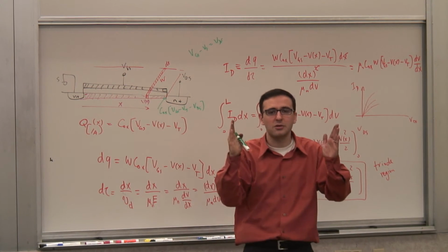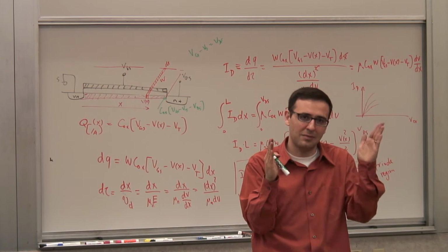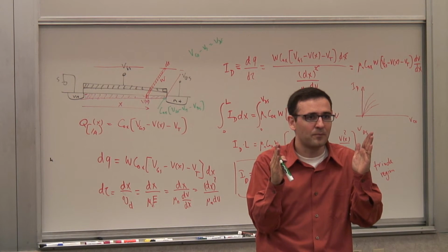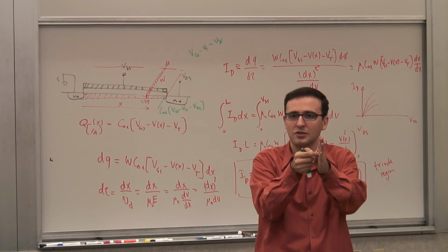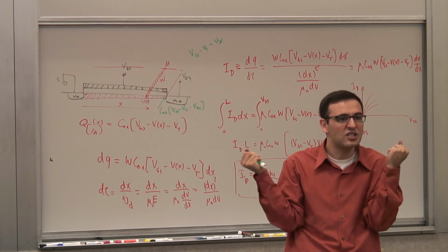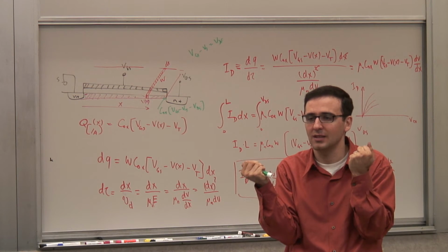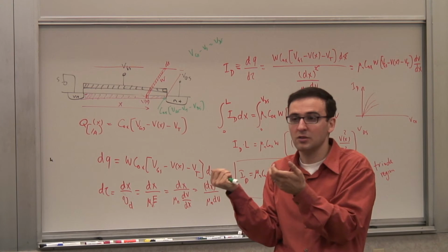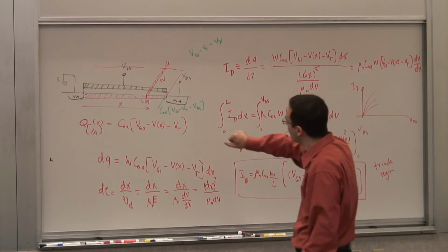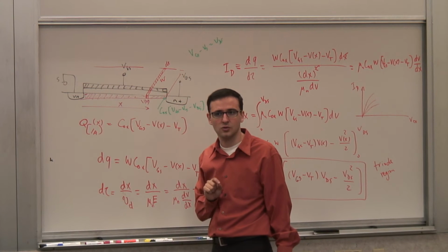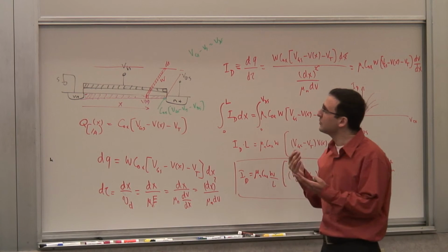The same way in the base of the transistor, you remember when we did this exercise, on the collector side, because everything that gets to the edge of the depletion region on the collector side is sucked in, the density is 0, because nothing can stay there, in steady state. But it doesn't mean there's no flow of charge, there's a huge flow of charge. It means that there's no net density associated with that point. Okay, so that's where we get to pinch off.